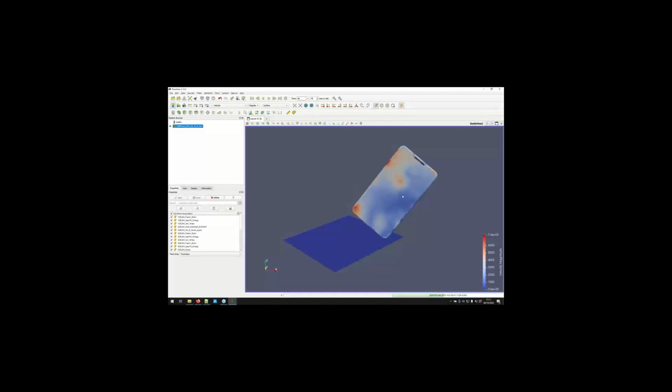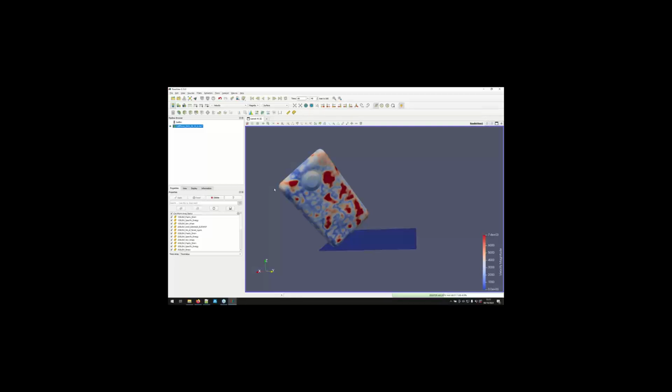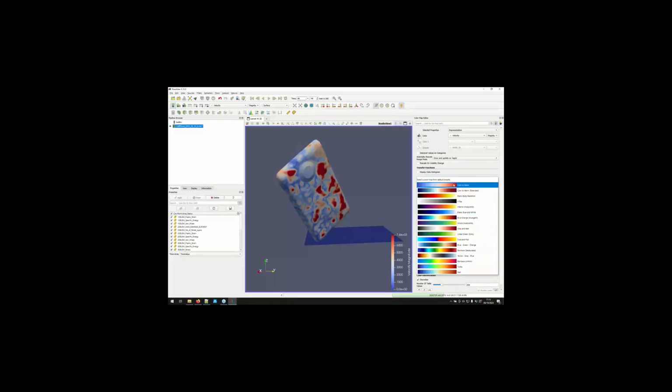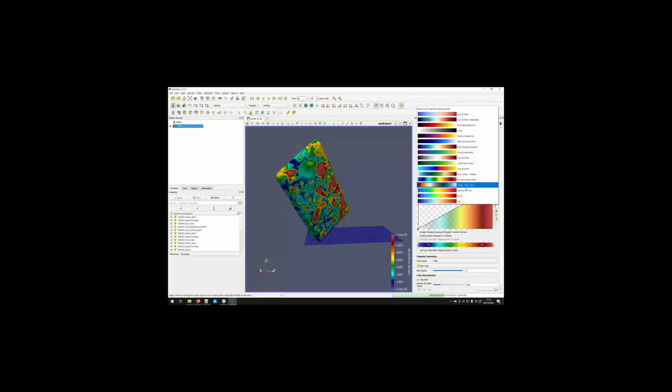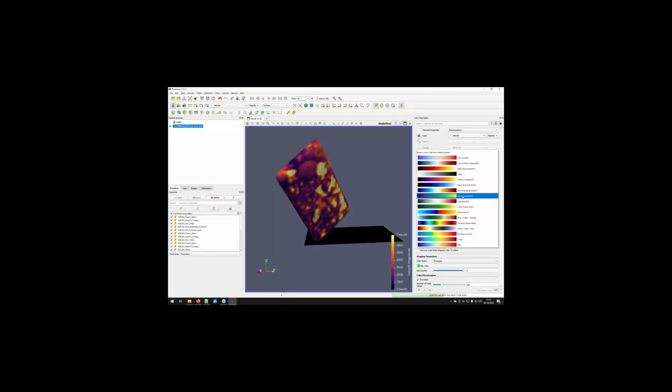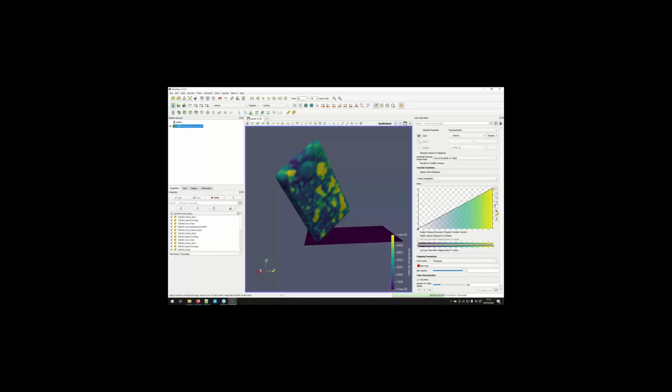Okay. So we can see different fields as we see. But the color is okay, but it's maybe not what you are expecting with an OpenRadioss explicit simulation. So with this button here, the edit color map, you can change the way you are mapping values to colors in the 3D view. It opens the color map editor. ParaView has a lot of color maps available. You have a few of them here as shortcuts. For instance, you can use the classic rainbow, or get some more modern ones like those from Matplotlib, Inferno, or Viridis. You can also edit it by clicking on the button.